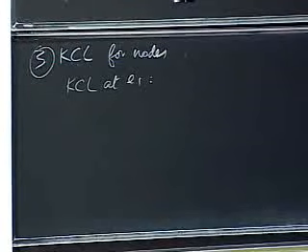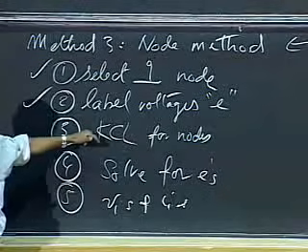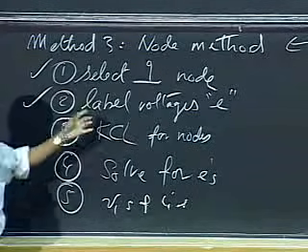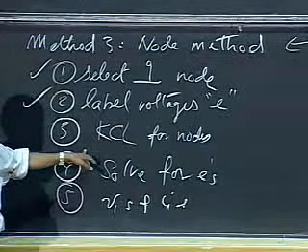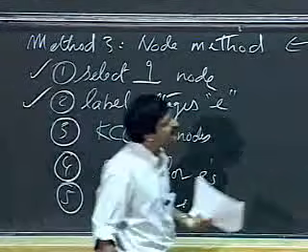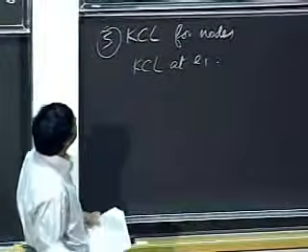Okay? So how do I write KCL? KCL simply says the sum of currents into a node is 0. Again, remember, by the lumped matter discipline. So the currents, but I don't have currents in there. So the trick that I adopt is that to write KCL, I use the node voltages and implicitly substitute for the node voltages, divide by the elemental resistance, for instance. So take the node voltages and divide by the resistance, get the current. Okay, so I implicitly apply element relationships to get the node currents. So the example will make it clear.